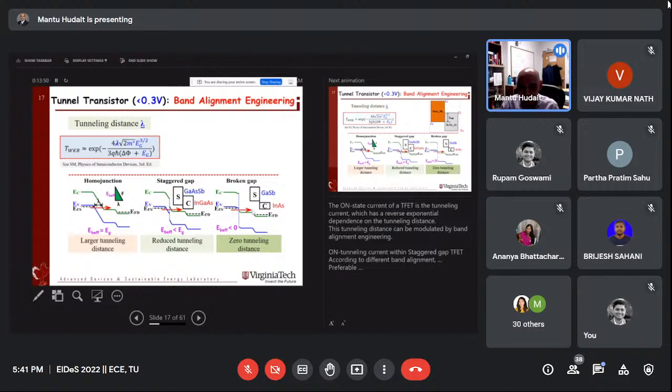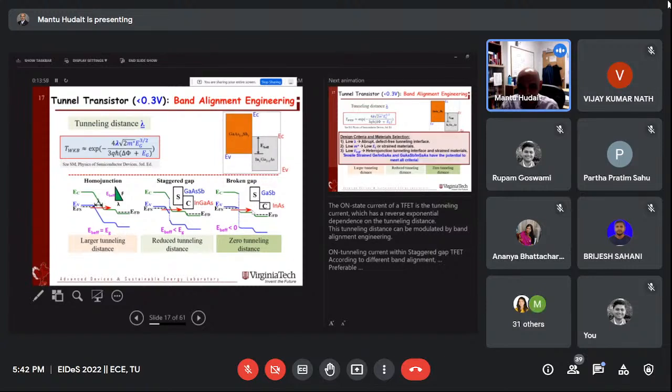So why not a homojunction? Because the lambda is too large. You want the lambda to be very small so the carrier can tunnel. Now look, this basically gives you the material stack of gallium arsenide antimonide, where the EV effective has to be small. What does Intel want? Intel wants 0.1. Why can this material system do it? It is lattice matched. It means if you have defects at the interface between gallium arsenide antimonide and InGaAs, we call it game over. It's done, it's dead.